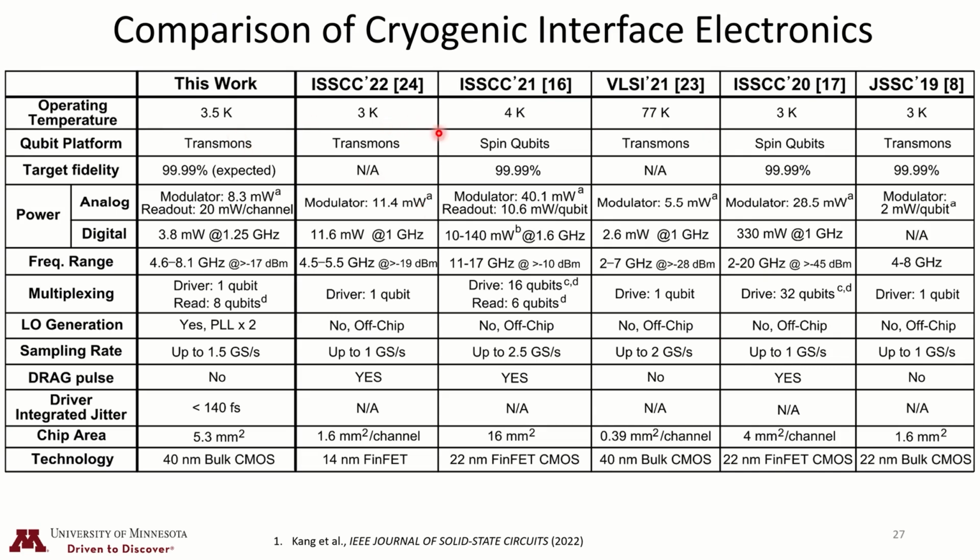And these kinds of cryogenic CMOS components are compatible with different kinds of qubits. It looks here that they are primarily associated with transmon superconducting-based qubits and also spin qubits as well. Perhaps there are some others aimed at other platforms, but these are the two primary ones that are compatible with cryogenic CMOS. And these are all the other properties associated with these different cryogenic CMOS components.